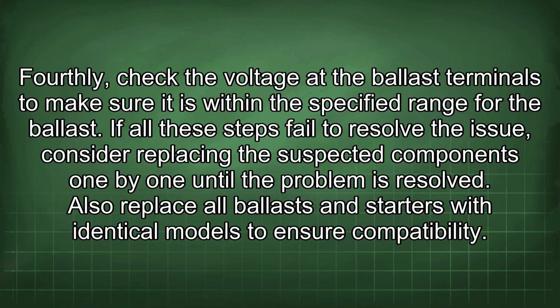If all these steps fail to resolve the issue, consider replacing the suspected components one by one until the problem is resolved. Also replace all ballasts and starters with identical models to ensure compatibility.